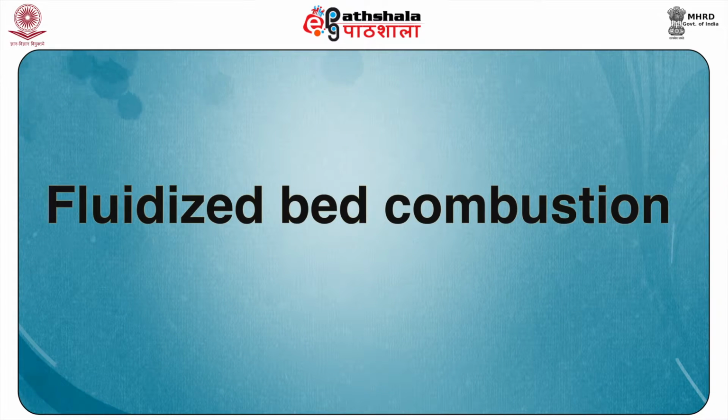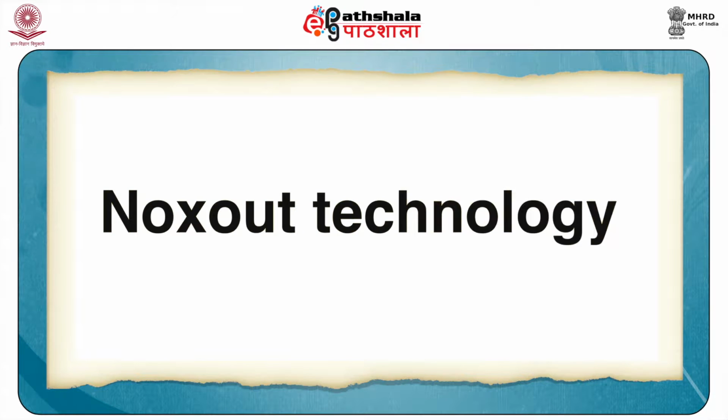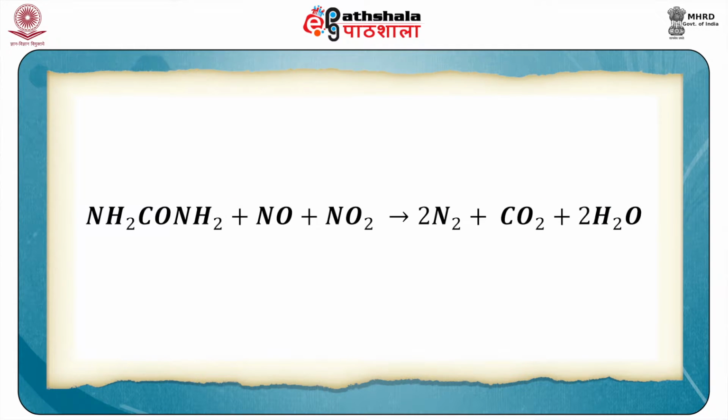Fluidized bed combustion. This process suppresses the level of sulfur dioxide from the flue gases after combustion. Limestone is added to the fluidized mixture to reduce the amount of sulfur dioxide emitted in the flue gas. NOxOut technology. It is a modern technology which uses urea to rid flue gases of nitrogen oxides.